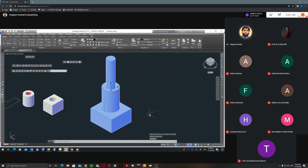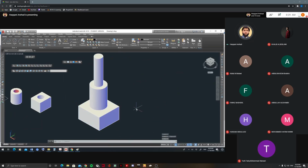So now it has become one part. So this is important when you finish the 3D model, you must do union. Okay, union is one command, just like join. Join we do in 2D, but this is for 3D. This is really important, union when you finish, because there are many ways to make a 3D object, and after making it, you do the union.